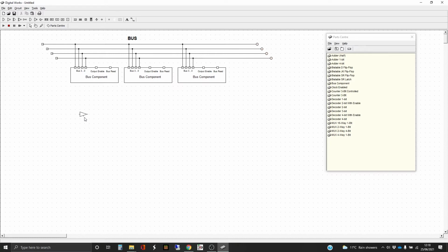However, it has an extra line which is coming in from below, and this is an enable line. And actually, unlike doing an enable using an AND gate, which is a kind of normal way of doing it in hardware, when this gate is not enabled, then it does not see this as an output. It actually is disconnected from the output, which means that we can have several things going to the same place. As long as we only enable one of them at once, then we're fine. Let's quickly demonstrate this with a little circuit, and then maybe show it in a broader context with the bus.